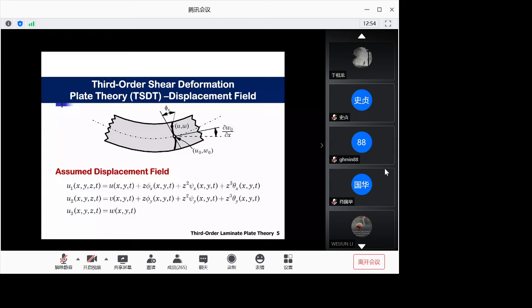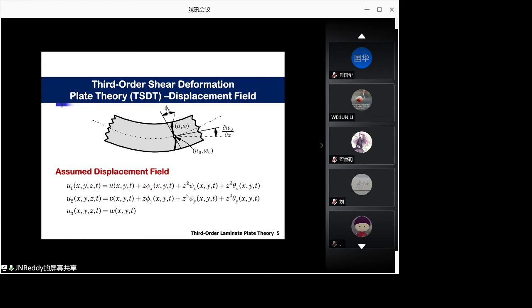So before I get there, this is one more time showing the through thickness of this plate. Before we were using straight lines remain straight, both in classical plate theory and first order shear deformation theory. But now we are saying the straight lines can become curves, whatever is dictated by the lamination scheme, but we are saying each layer does not strain proportionately, but they can change depending on the individual stiffness.